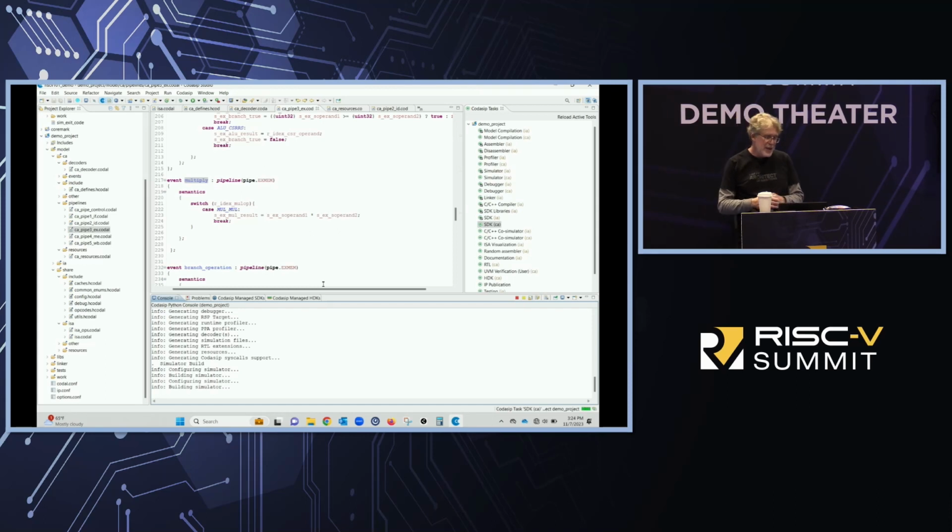Now, if you wanted to go a little lower in the microarchitecture and not consume as much area, you could define a serial multiplier. That would reduce the area, but then you'd have to have a little state machine that says how many cycles it takes to complete the multiply. But for this demo, I'm just going to do a very simple parallel multiplier, because the real idea here is I just want to show you how you can add another compute element.